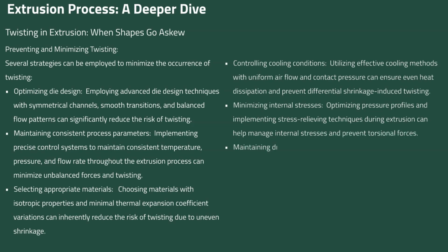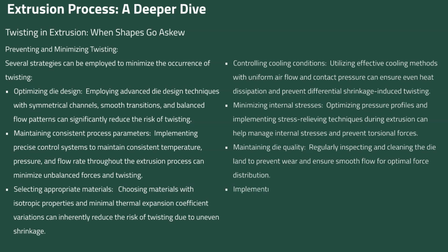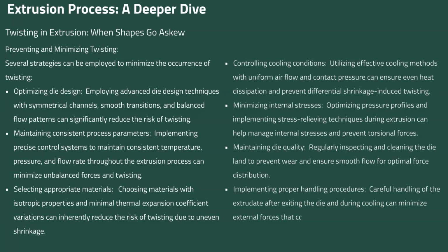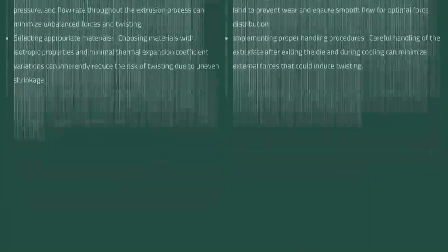forces. Maintaining die quality. Regularly inspecting and cleaning the die land to prevent wear and ensure smooth flow for optimal force distribution. Implementing proper handling procedures. Careful handling of the extrudate after exiting the die and during cooling can minimize external forces that could induce twisting.